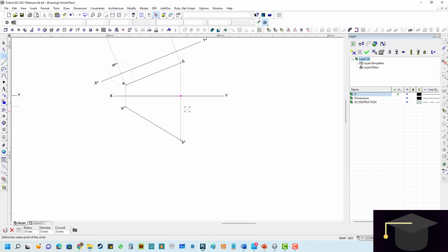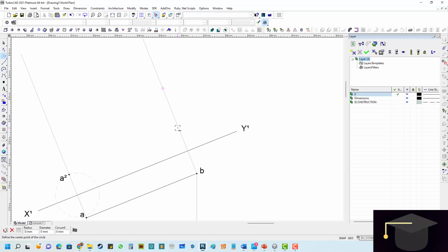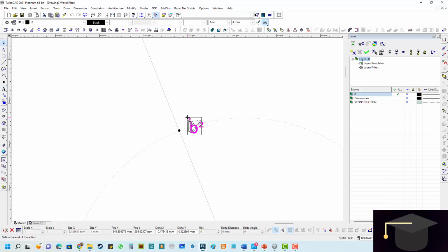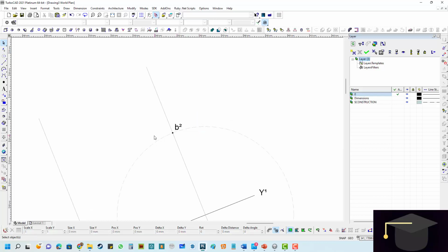So we're going to take that 40 millimeters, follow the line's construction or projection, and from here go and say 40 millimeters. Once we've done that, we just place the reference point and press I. There, that's placed. Select the text tool, click just off it, and we say B and then Alt 253. That will give us B2. Once we've clicked off of that, we can place it in the right position.